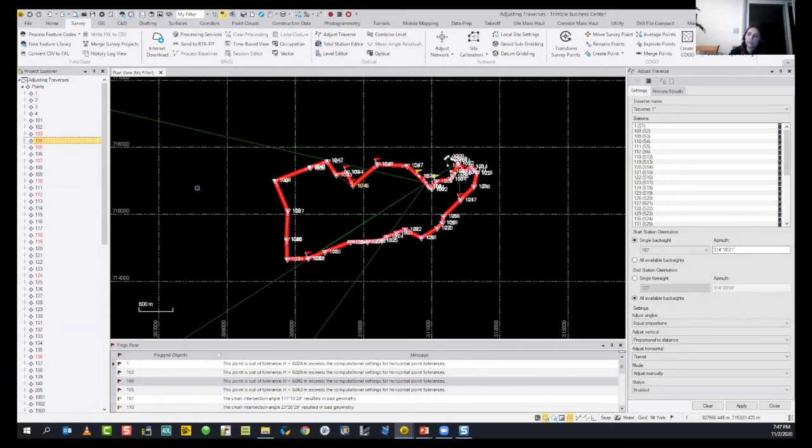the reference stations, and you can bring your NGS parameters over the internet download and apply all of them. Then you can apply the network adjustment. You can also perform transform survey points, merge points. It's possible to apply the site calibration after we finish everything. And we can change the local site settings for scale factor change. All these processes can be applied under one project.